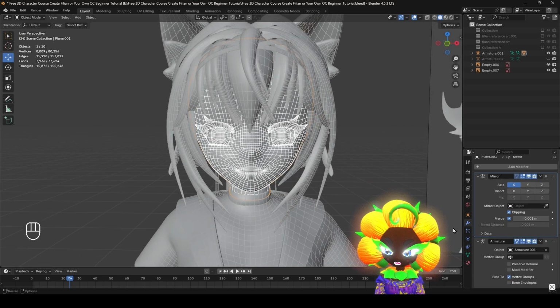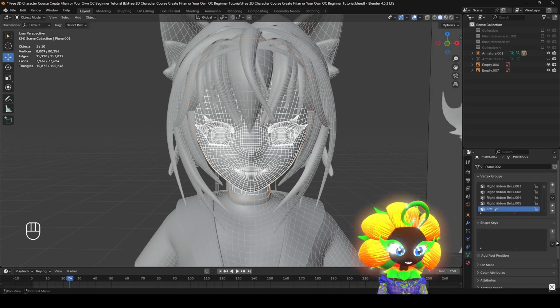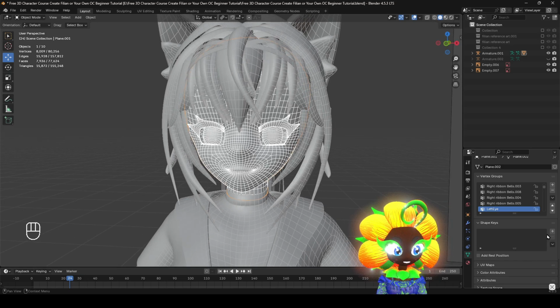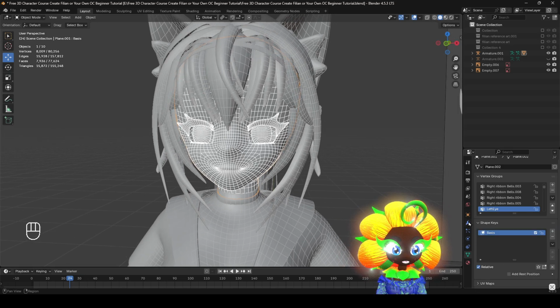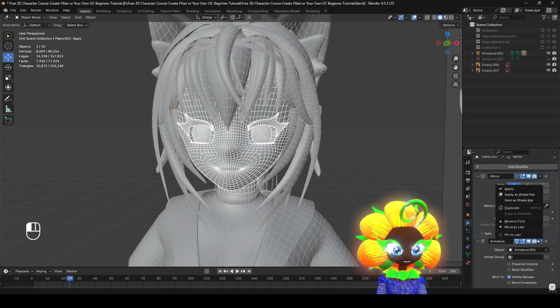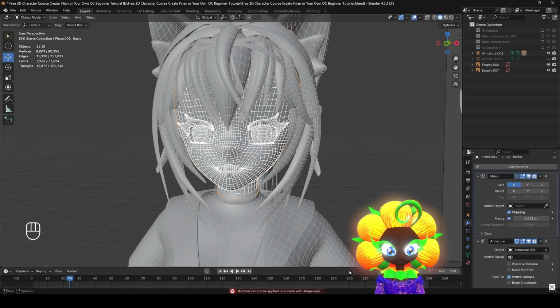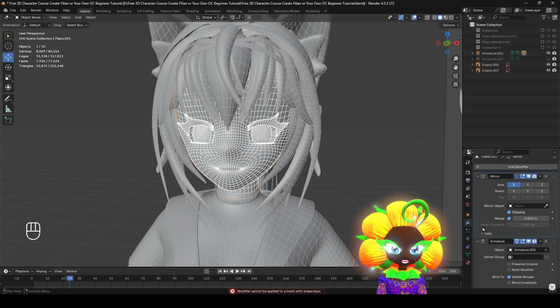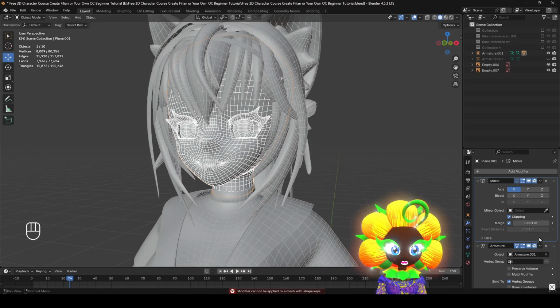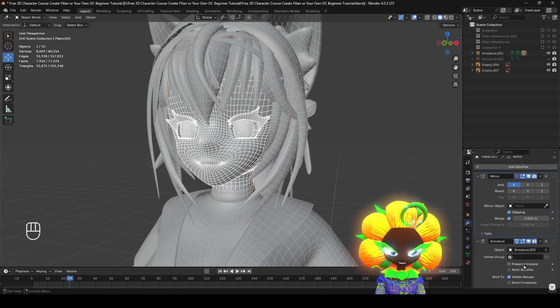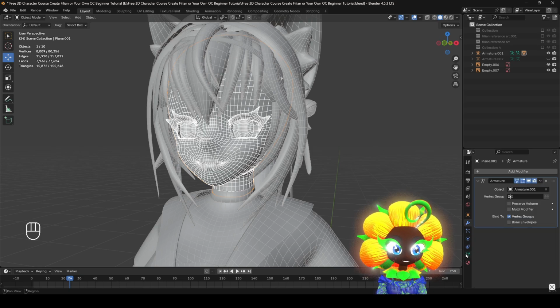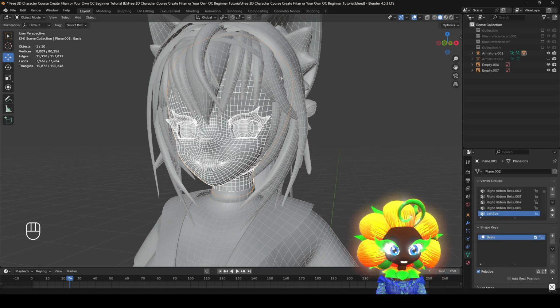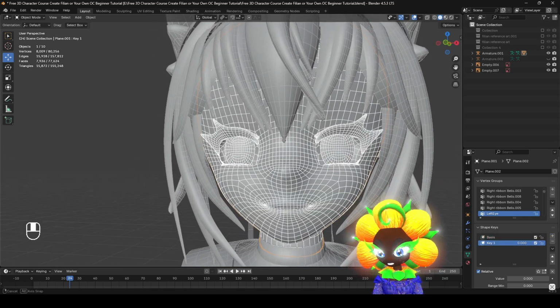And when you are doing the data for shape keys, you can't have modifiers. For example, if I were to click this and go up to here and try to apply it, see, this warning comes up. All right, it's having a fit. So I'm just going to have to exit it. Then I'm going to go up to here and apply everything, except for the armature. That doesn't have to be applied. Apply, then go to data, then apply. Okay, we click 2. We don't want to touch your base. And this one, we can start with, I guess.